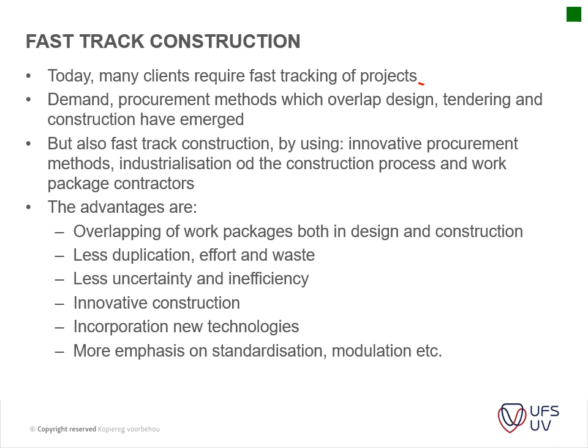For instance, the drawings might not be complete yet, and you have to develop bills of quantities. I've had to do that quite a bit. It becomes provisional because the design isn't done, and only during the appointment of the contractor is the design finalized.